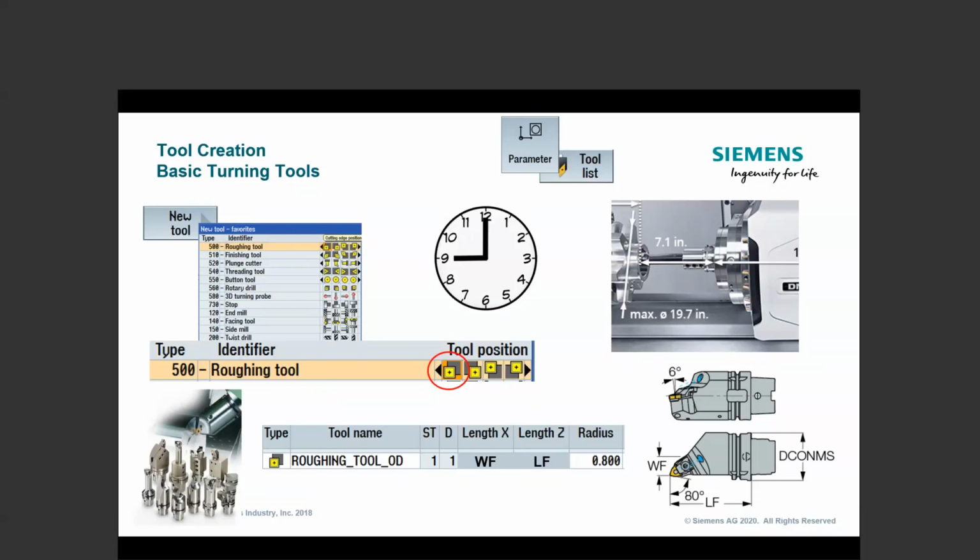How it looks in that machine should match that picture, and that picture should be a tool that can perform an OD turning operation. Now, as we start to move things around with the B, it's going to automatically change which orientation on the fly. So we're going to get there, but this would be step one. How do I build an OD turning tool? Well, if it's a right-handed tool, when I'm sitting at B0, I would choose that first cutting orientation.